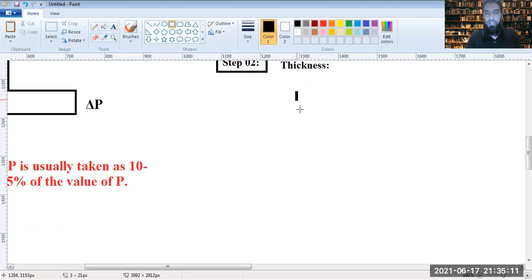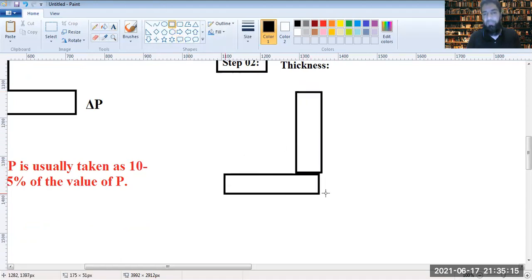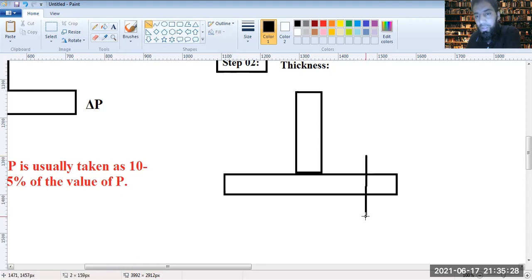First is the one-way shear, that's acting at a particular distance away from the column from which the load is being transferred, and on both sides of the column, this one-way shear would act along the longer direction.